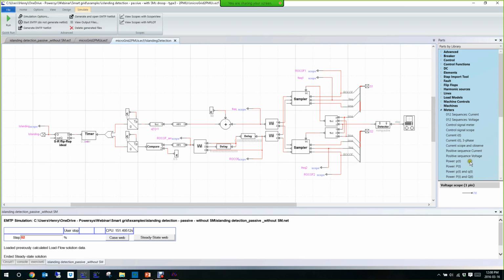So what do we do? Okay, here, anytime we receive a new thread, we synchronize it. If the time of the two threads doesn't correspond, which would mean that one thread didn't arrive for some reason, we don't consider it. And so we wait that the time of both are the same to take them into account. And you see, then we do a sample of them. Okay, so then we take an average value of both, and we look at the frequency deviation here with a small delay, and then here the rate of change of the frequency, and we actually do an average on one period. Okay, and we add the delay again. So here what we do is the PMU, the synchrophasors are refreshed. I think it's twice a cycle.